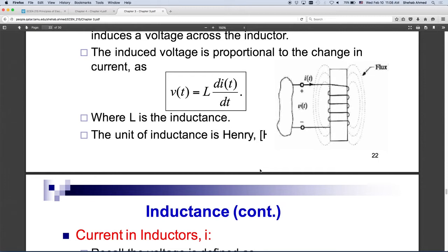Same thing with the inductor. You keep trying to push current to increase the flux stored around the inductor. The material that you have this flux confined to has a flux carrying capability, and it will saturate. Right? So after some point, you've pushed the maximum amount of flux that you can push through a certain material. After that, you're doing what? You're just pushing current for no reason, because you're not getting additional flux, because your core has already saturated. The path that you've defined for the flux to flow has filled up. So you can raise the voltage.